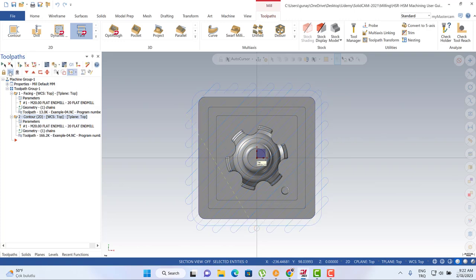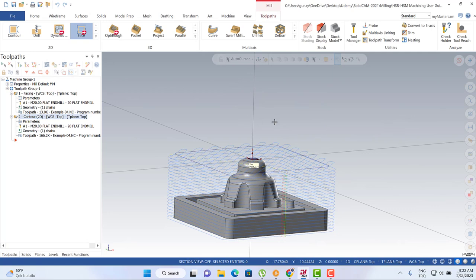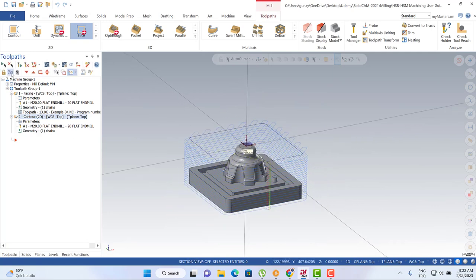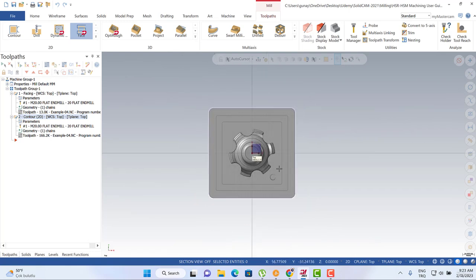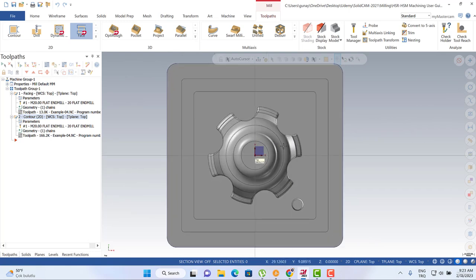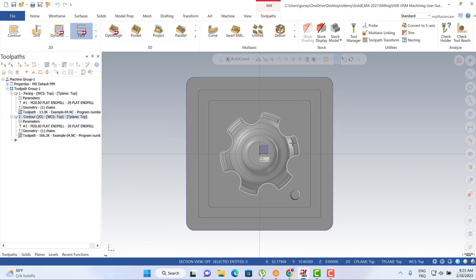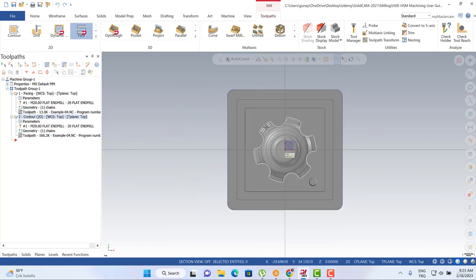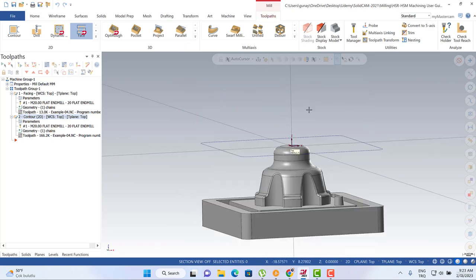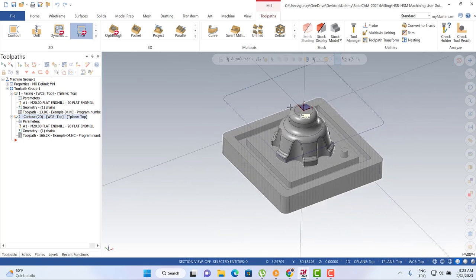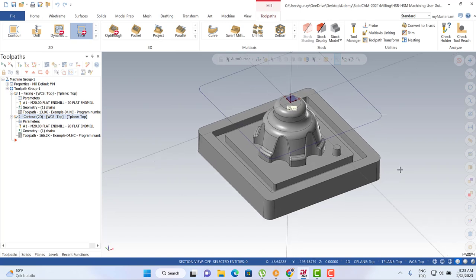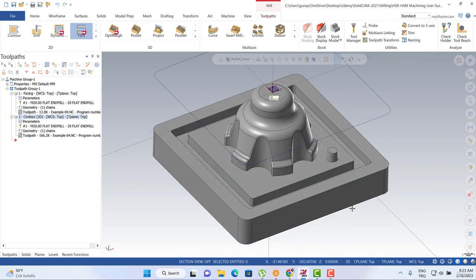As you remember, we are creating some face toolpath and contour toolpath. And after that, when I'm looking at my product, my design, that's quite important. If it is possible, I prefer to use the 2D toolpath. It is also quite easy for me to select all that part and create some roughing process. But most of the time, I prefer to use the 2D pocket toolpath.